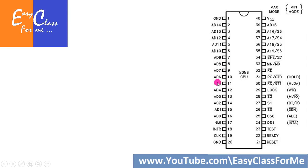Now, after we have discussed these multiplexed address and data buses, we come to these pins. This is the clock pulse which we have seen in the previous lecture. We require a 5 megahertz clock for 8086, although there are 3 different variants: 8086 itself, 8086-1 and 8086-2. 8086 uses 5 megahertz, 8086-1 uses 10 megahertz, and 8086-2 uses an 8 megahertz clock. But for our purposes, since we are dealing with 8086 which has a 5 megahertz clock pulse with a duty cycle of 33%, that input has to be provided at this clock pin.